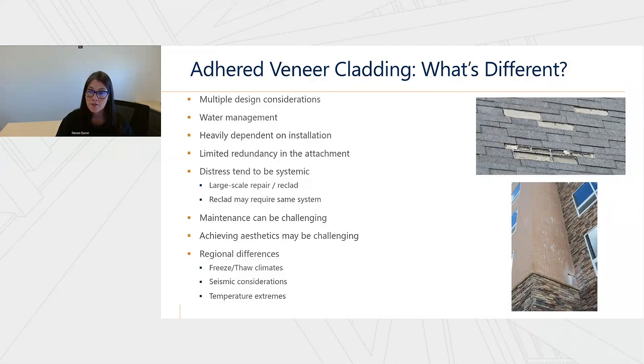Also, just making sure that the flatness of our substrate is there, because again, since we're adhering these veneers to that substrate, if we have waviness or we don't have a straight corner, that's going to be seen in the final application. And then finally, just regional differences to consider, such as freeze thaw, seismic, even temperature extremes.